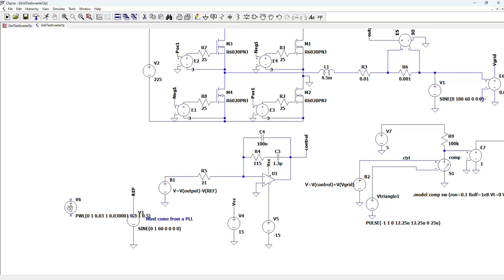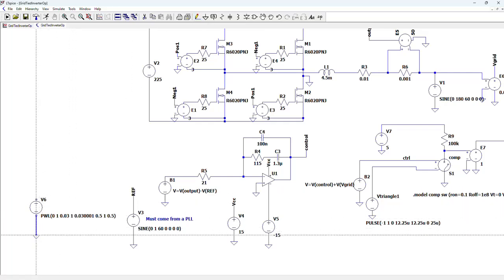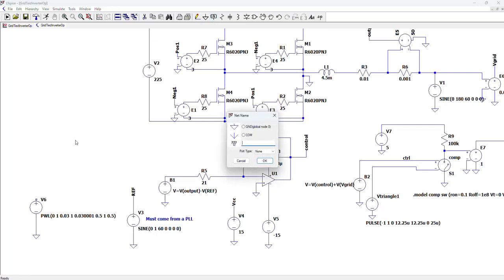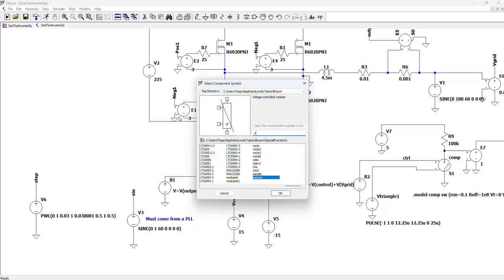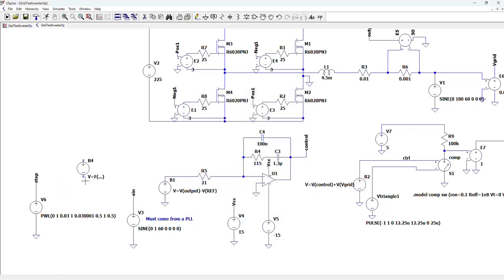to 10 amps. This is a test that is good to apply because the controller is usually designed around an equilibrium point, but we're going to see that this linear controller also works well at a different operational point without modifying its parameters. This is the step. Let's define a variable called step, which is just our step. This I will change to sinusoidal, and I will include here a behavioral voltage to multiply these two voltages, and this will be my new reference.